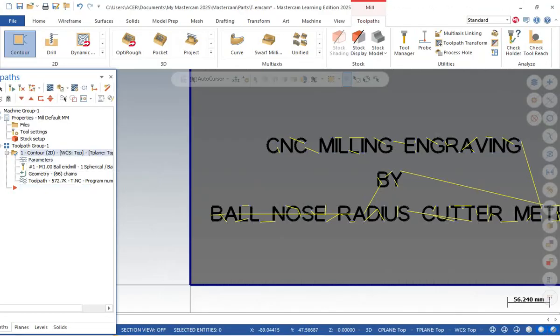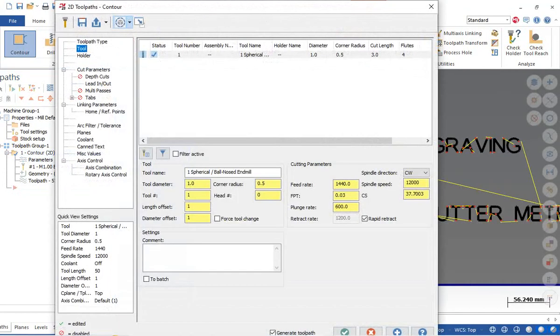Now again go to parameters. Here feed rate should be 600 to 700. For RPM, we should work with 7000, because it is a 1 mm ball nose. It will not take much material. It will take 0.05 material, because since it is a ball, it will directly hit the workpiece. It may be broken. So it is not an end mill. It directly hits and takes the material.